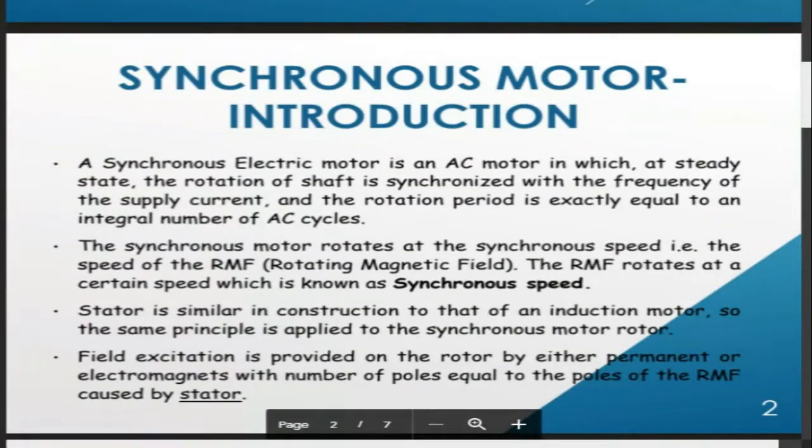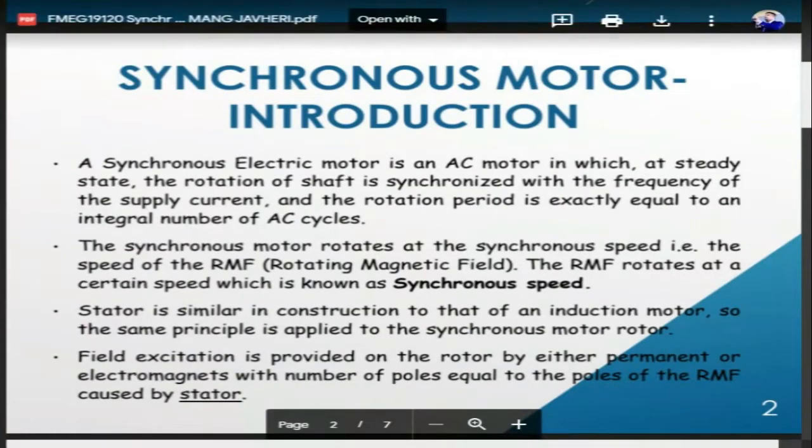Okay. Now this particular synchronous motor has another advantage, or another effect: it provides an excitation-based power factor. Now what do you mean by that? If you increase the amount of excitation given to the rotor circuit, or we can say if the magnetic field strength of your rotor is increased, then the motor will possess a different power factor.